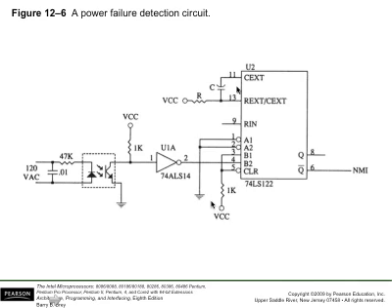After this inverter, we'll have a 0, so that's a change from 1 to 0. As a result, this Q bar will have a change from 0 to 1. So that's a rising edge, and that's exactly the trigger we would like to have to notify the microprocessor that a non-maskable interrupt has happened.